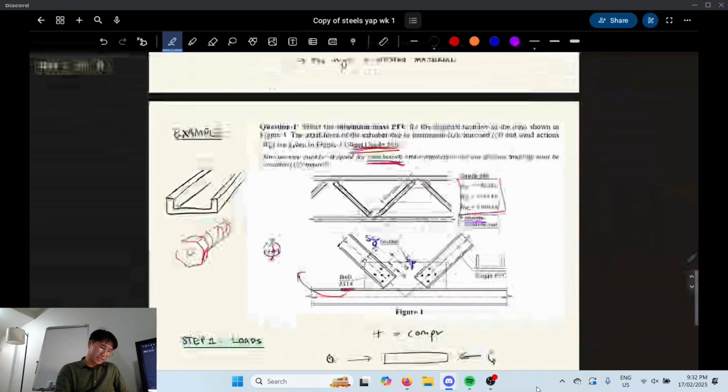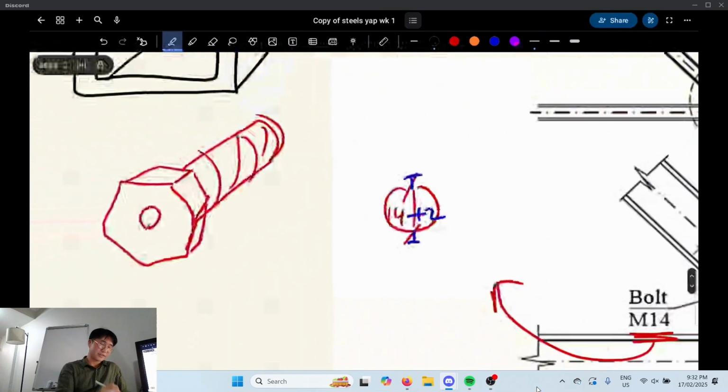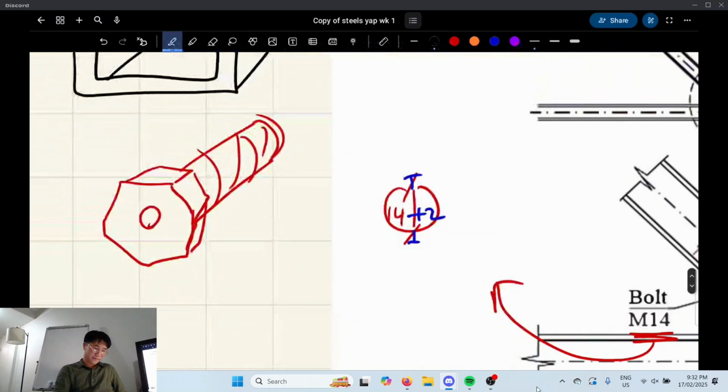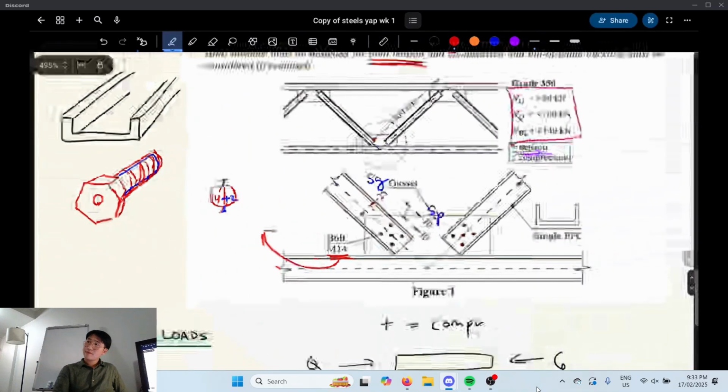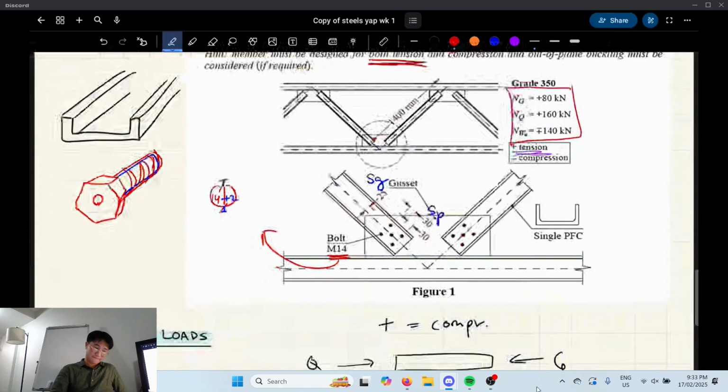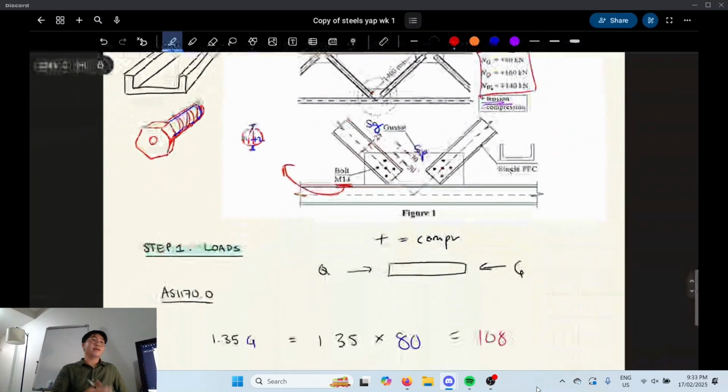Oh no, it's the actual geometry of the thread pattern. Because the bolts have that inner core diameter, and that's 14, and then the threads are the extra 1 on each side, which is 2. So that's the hole size. Basically, every time you see an M bolt, you add on 2 mil. Exactly. So the +2 is the spinny stuff. Yeah, pretty much.